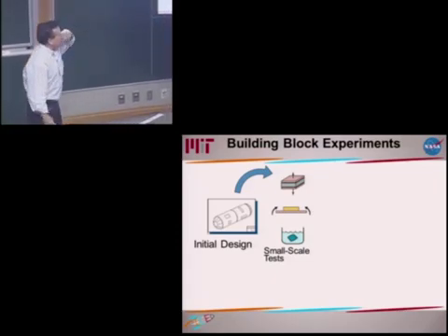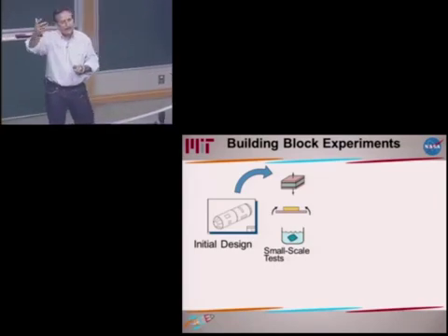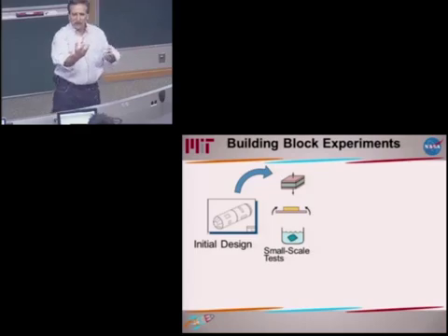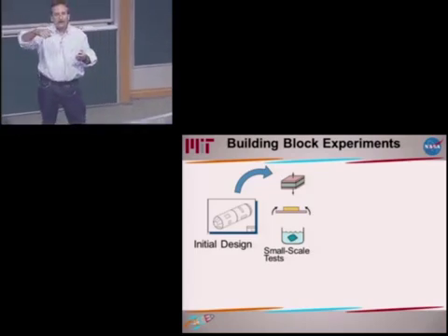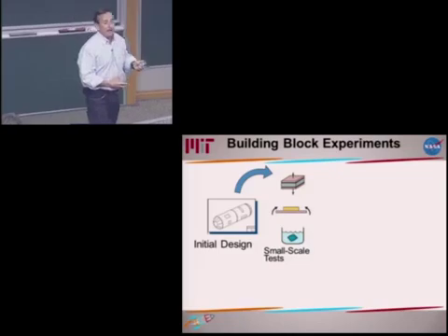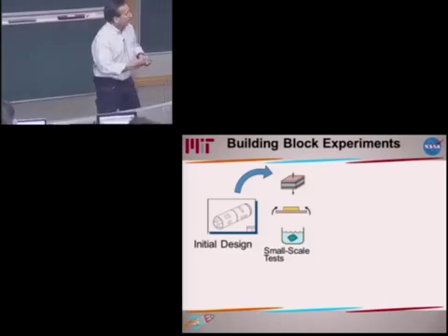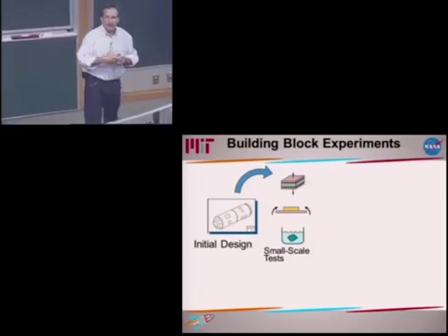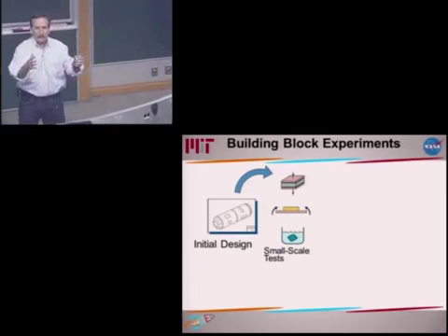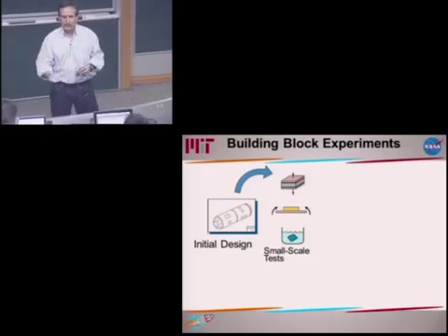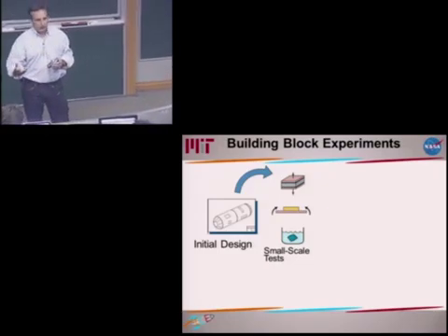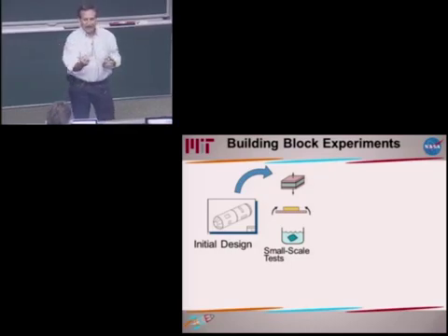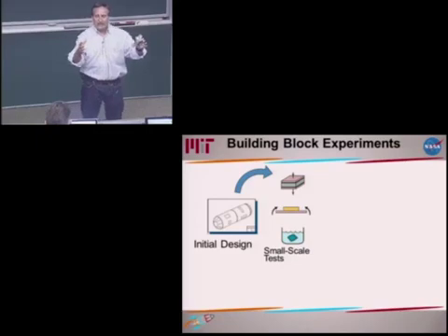These simple figures represent a concept, an idea that we had for a reusable cryogenic tank. You have cryogenic hydrogen, but we wanted to create a rocket that you could fly to space, bring the tank back, and reuse it. Never been done before. Minus 420 degrees, we said, you know what, let's use a sandwich structure, and we'll evacuate that sandwich, so we'll make it like a thermos bottle. So that structure, and this is a term you're going to hear, will be multifunctional. Okay, it will act as a really efficient structure, which honeycomb sandwich does, but we're going to evacuate it, and now it's going to be a great insulator.